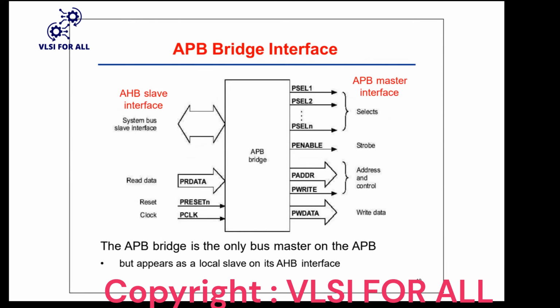Okay, fine. So this is how you will make sure which slave is going to get selected. Basically, each slave will have a dedicated 1 KB boundary, a boundary condition. Each slave will have 1 KB of space allotted to it, with an address range from 0 to 1023. And if the master issues an address that falls in between that, that particular slave will get selected.